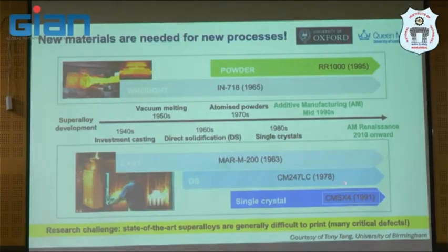We usually refer to CM247 because this is a material optimized for directional solidification. Directional solidification is used a lot in the aerospace industry because of a high volume fraction of gamma prime, 65% or a bit above in nominal composition. 718 is actually an older material, from 1965, but it is very superior in the sense that it is used a lot in the aerospace industry. No one can replace it yet.